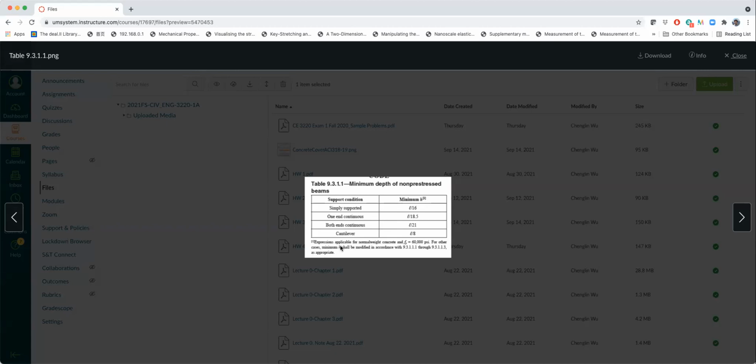You see it? Yeah. So my 18 and 12 estimation mainly comes from my experience in ASCE code as a beam deflection criteria. And that has something to do with design philosophy, because if your height is too deep, then you don't have a beam type of behavior for your structural members.